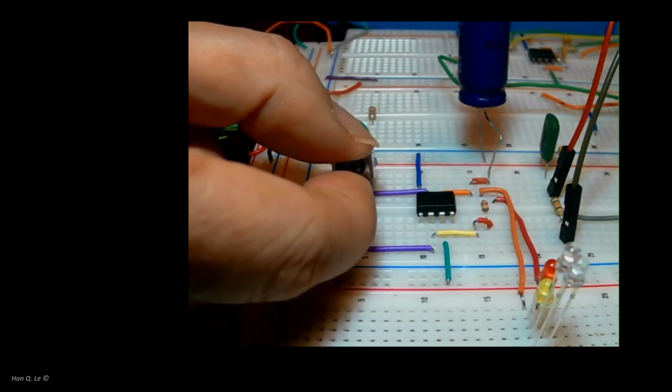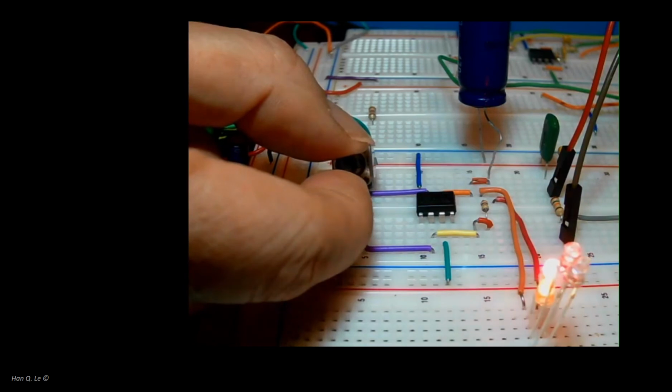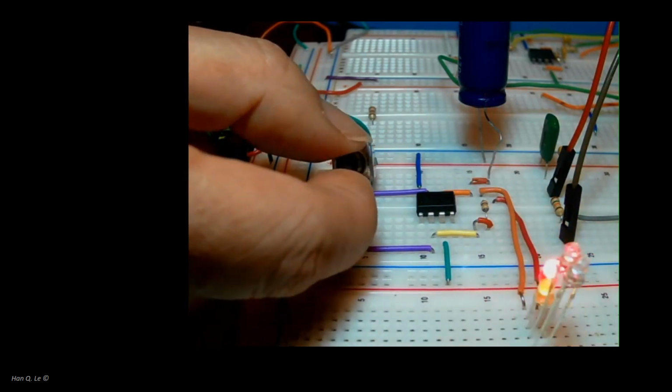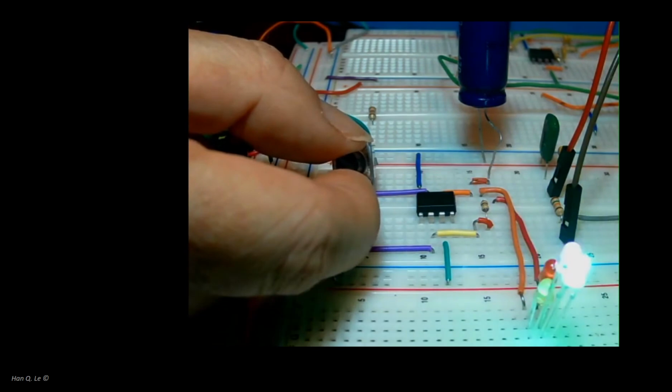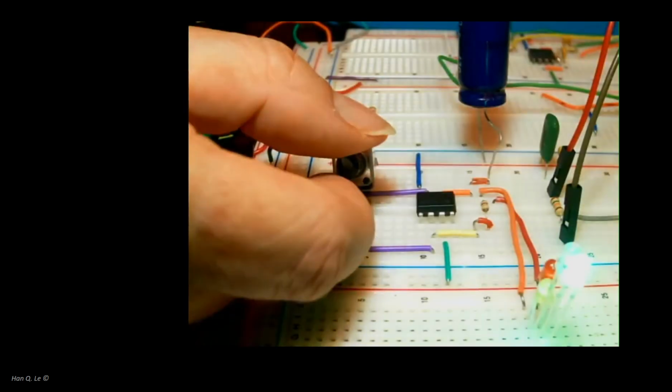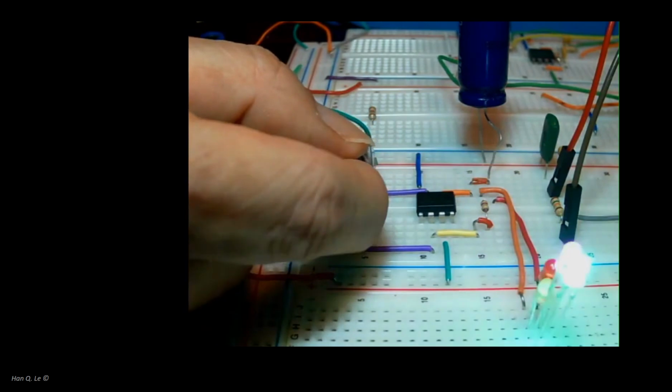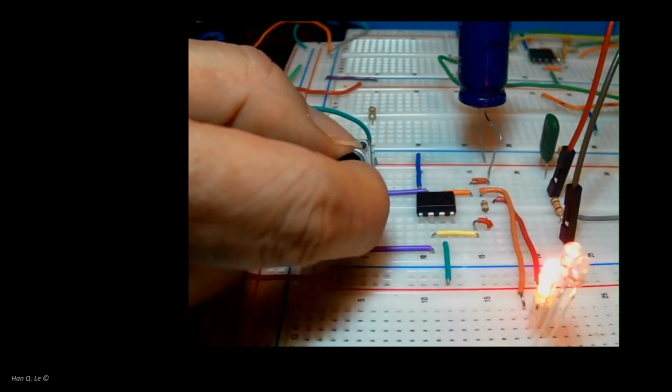When using LEDs in parallel, they all should be of the same type. Here they are not, but the group of low band gap, that is orange and reddish, are grouped together, and the high band gap type, green, blue, and white, are grouped together. At high frequency, the camera, which is 25 frames per second, can no longer accurately represent the blinking behavior, which is why in a later video, the photoreceiver of Lab 4 was used to measure the LED light output behavior.